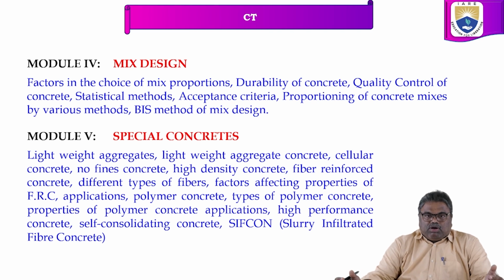We will use this concrete where the concrete cannot go inside, where there is too much reinforcement and a vibrator cannot go inside the reinforcement. In those particular places, we will use self-compacting concrete. Since the concrete is itself compacting, we are not going to use any external vibrator to compact the concrete, right? So this is self-compacting concrete.